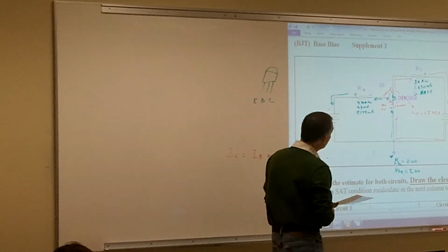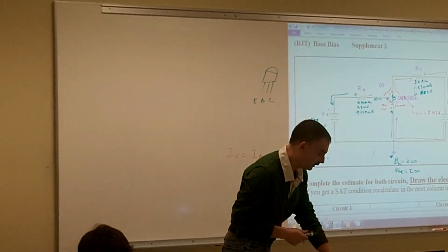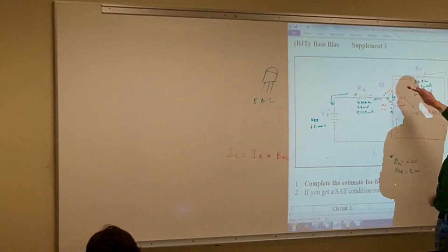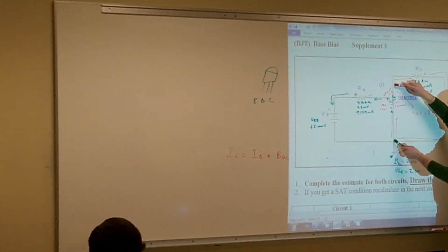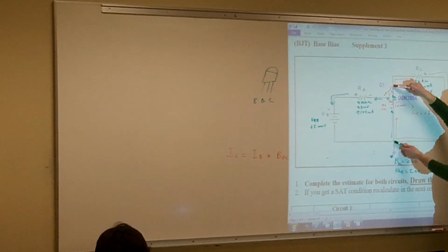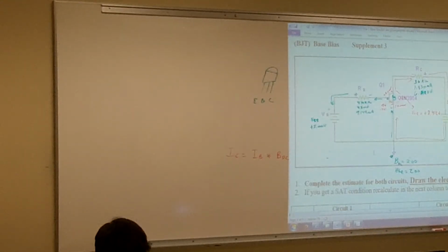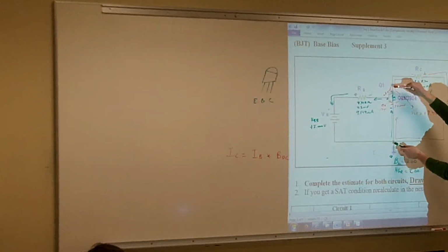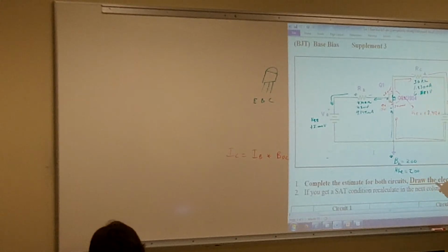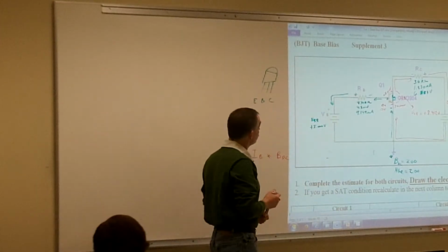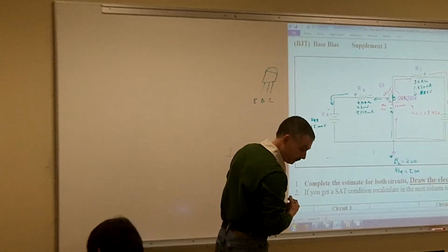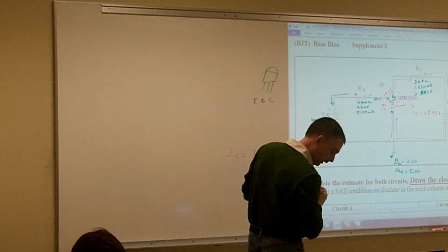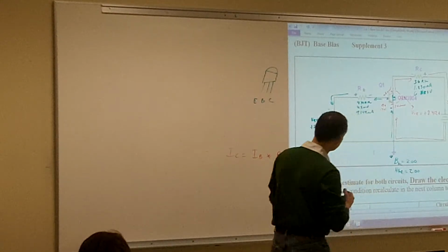So what's going to be my voltage from my collector then? So another test point. Here's my collector. My red lead goes here, my black lead goes here. What's my voltage of my collector going to equal? Plus 8.412. Okay. And that can change depending on what we have for a configuration of our transistor. But in this case, it's the same as our voltage CE since our emitter is tied right to ground. So VC then is also going to be a positive 8.412 volts.